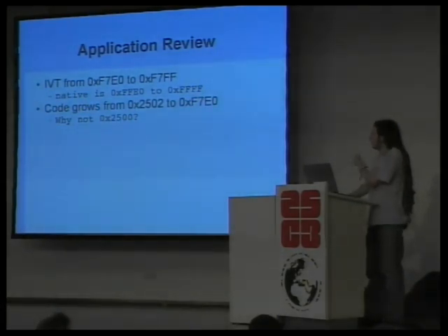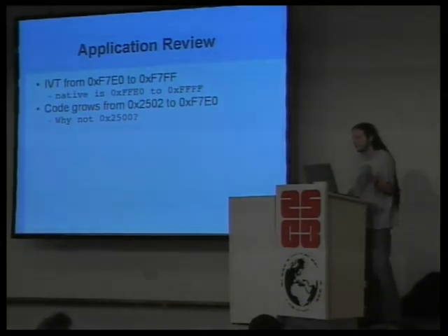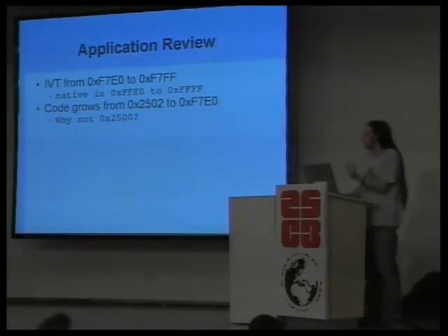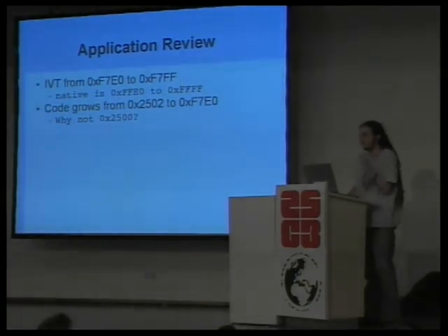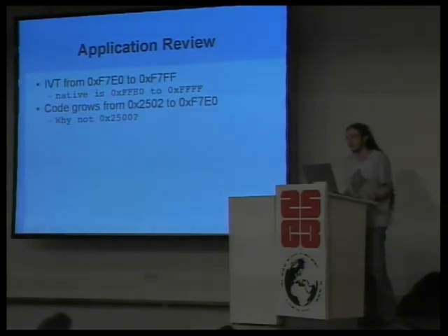The interrupt vector table entry for the reset vector is ignored, and instead execution jumps to 2502 hex. The first word of flash memory is always left empty, and execution always begins on the second word of flash memory on this firmware image and only this firmware image. If you look at any other image from any other compiler, execution will begin at the very bottom of flash memory.